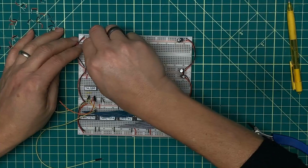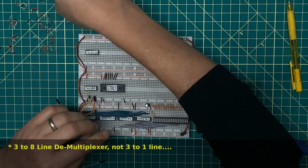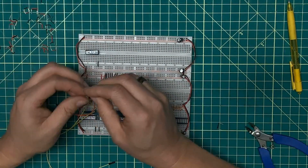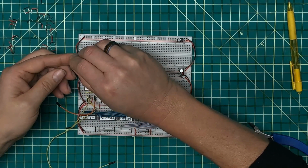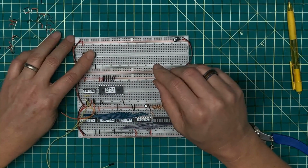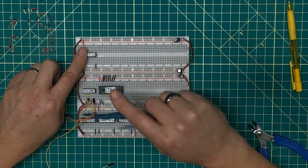This is a 74LS138. This is a 3-to-8 line demultiplexer. And this is what I've done a lot of analysis on and reading of the data sheet in order to understand the timings and everything. And this one I'm going to use for the address bus 1 assert. Because it's an address bus 1 assert, it's going to be on all the time.